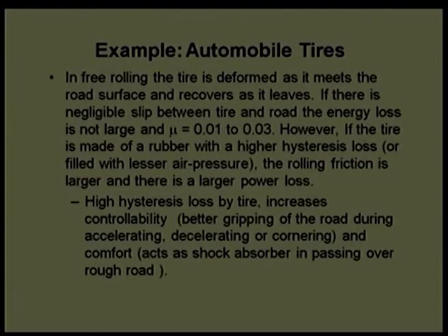But if we require very high reliability, definite life, definite fatigue life with high reliability, then in that case we should prefer the rolling element, or rolling friction compared to sliding friction. When we discuss rolling friction, we are adding one more thing: when we take the example of a tire, we need to see whether the tire is completely filled with air or not.